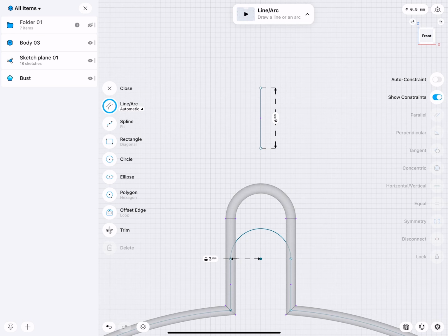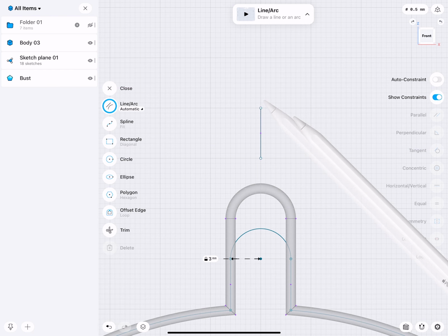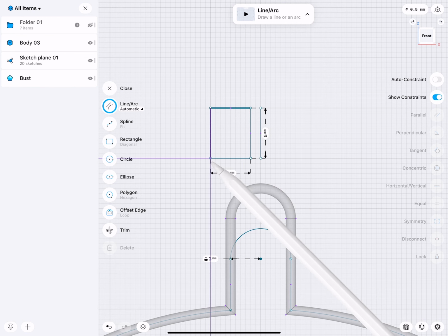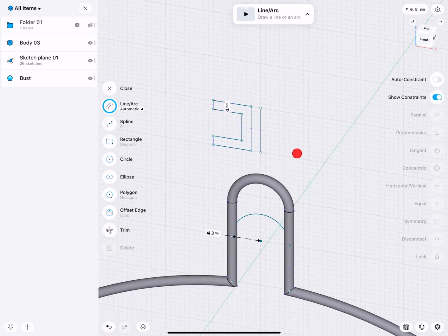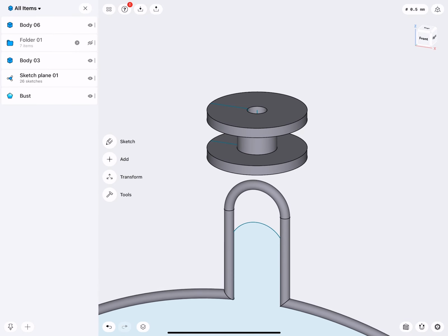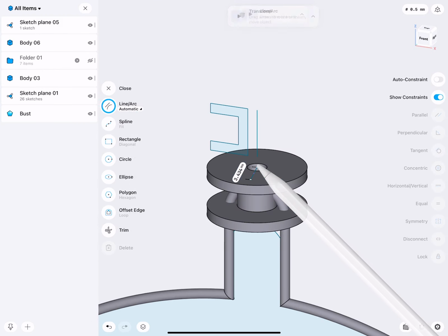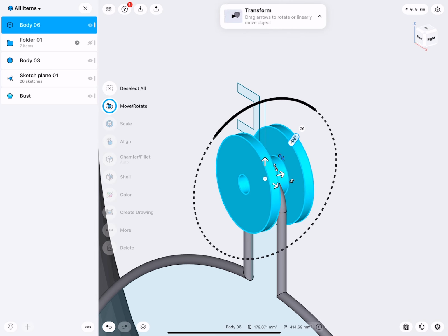So here's my center, and I would like to create a revolve object. Bring this down, that is 5 millimeters. It's actually interesting to measure body parts, so how thick is something. So let's go with 5 millimeters. And here I draw a very simple C, like this. Okay. And then I can take this and revolve there. Okay. So this I will bring down and then I will rotate it 90 degrees.